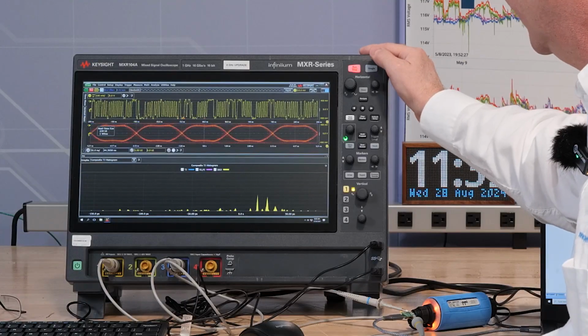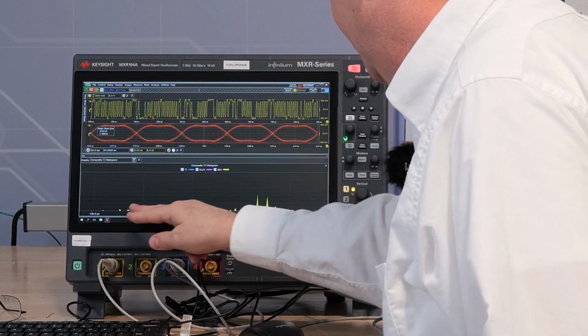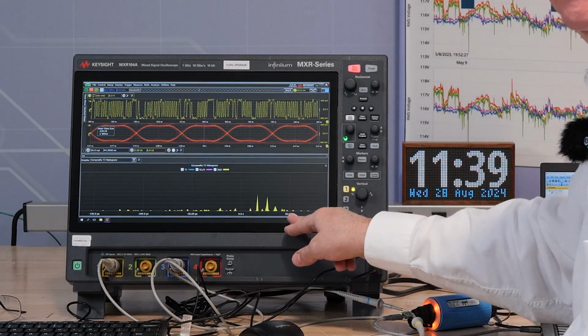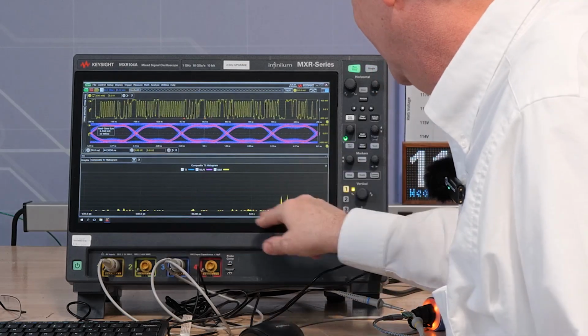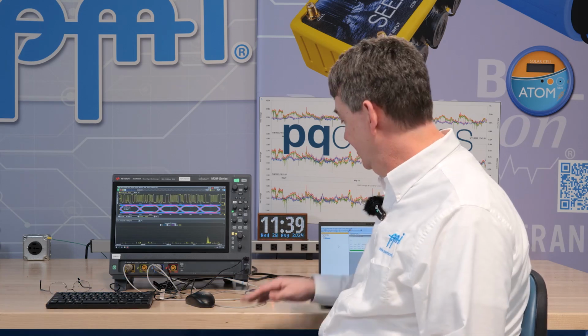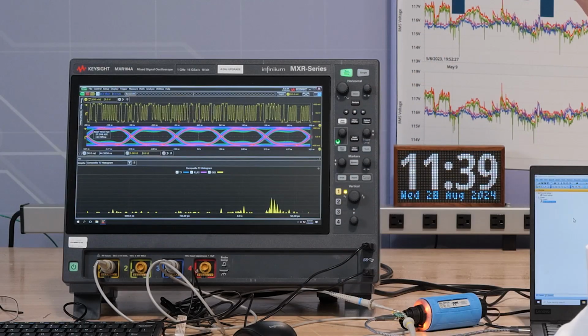I'm going to freeze this and take a look at the jitter, and we can see we're about minus 100 picoseconds to about plus 50 picoseconds of jitter. And if we let this run, we can see that the measurements are still within that range, no more than plus or minus 100 picoseconds of jitter on a 2 nanosecond pulse width, which is well within the USB spec, which means that the Bolt is emitting good pulses with good timing, allowing the host to do clock recovery and bit detection correctly. So we tested the physical layer of the Bolt USB interface.